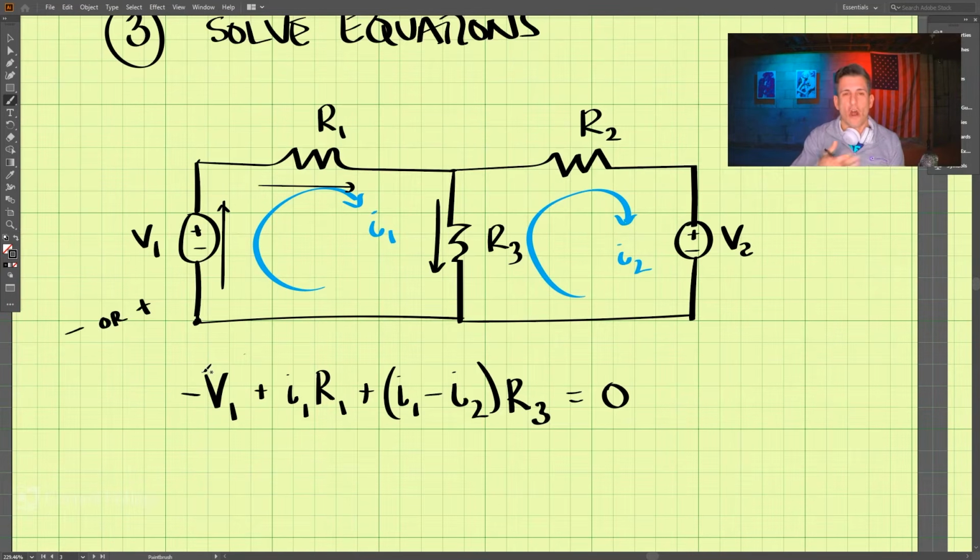So it is just our choice to pick this method where if we go this direction, from negative to positive, we call that negative. And we call the voltage drop from positive to negative, we call that positive here. But it is our choice. We just need to be consistent. We need to say the same. Okay? And now we can go and do this second loop here.